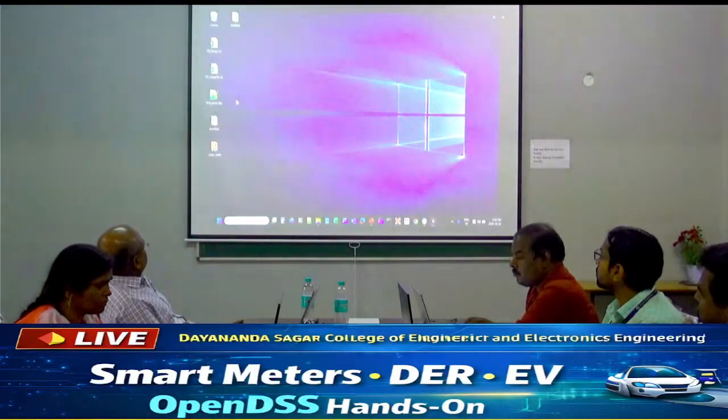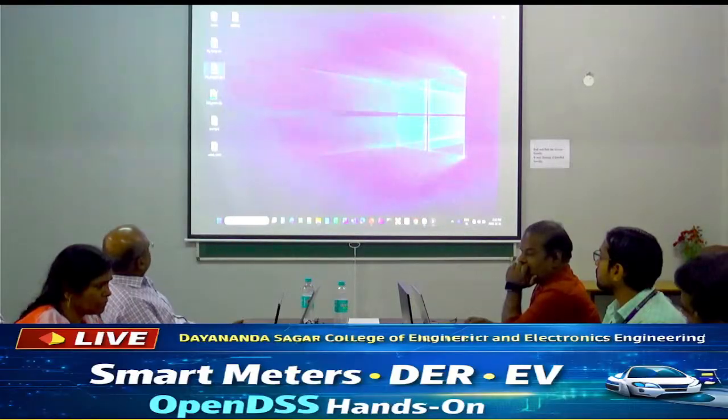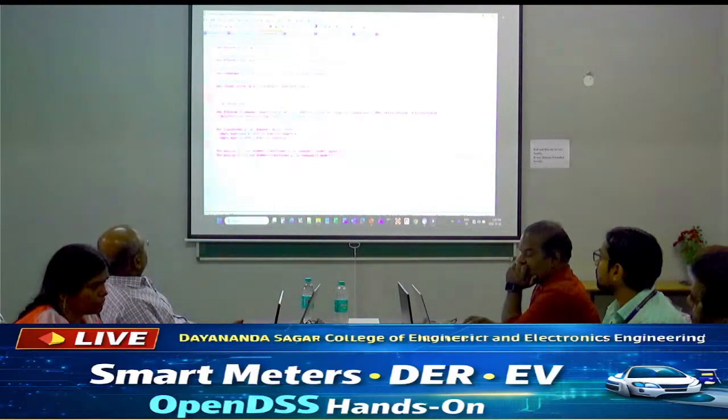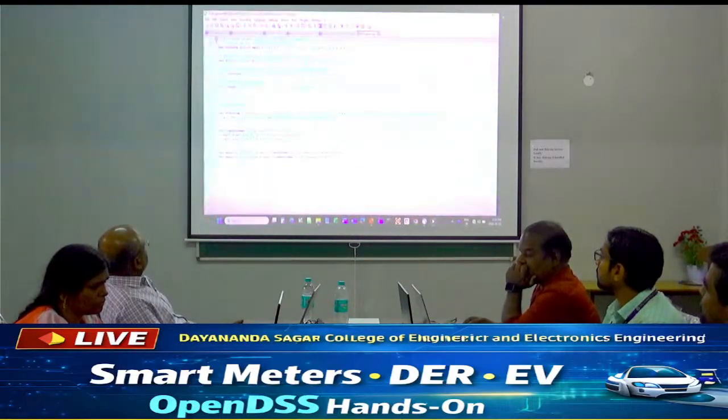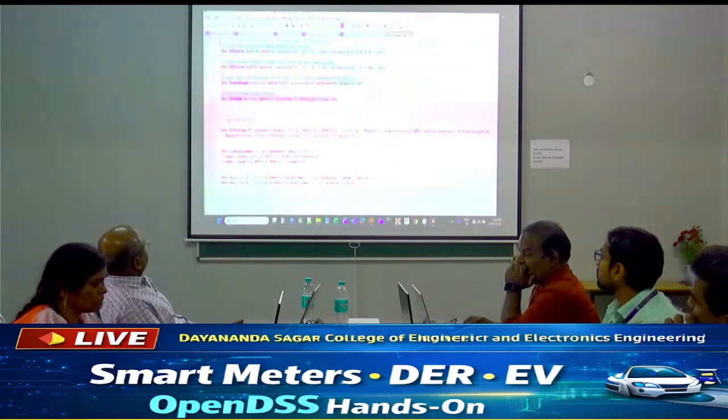Now, we will add a PV system. We have prepared these three files here that describe the PV system. One of them is a DSS file, the other two are CSV files. Let's take a look at the DSS one. It basically describes our PV system, including its characteristics such as power versus temperature, efficiency, irradiation, and temperature curves. These last two are in the CSV files.